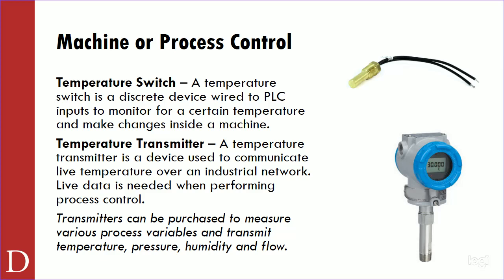What's the problem with some of those other transmission variables like voltage? Losses, noise, all of those are problems, right? A lot of times we talk about a 0 to 10 volt analog signal, and we have that scaled or proportional to 0 to 100 degrees C. Works out really nice. 5 volts is 50 and 7.5 is 75, and you can do that really easily. But the problem is when you send that 10 volt signal over a line, Mike's right, we've got to make sure we don't have noise affecting that, because if there's noise on the line, I can literally move that thing up a couple millivolts or down a couple millivolts, or maybe several millivolts, right?